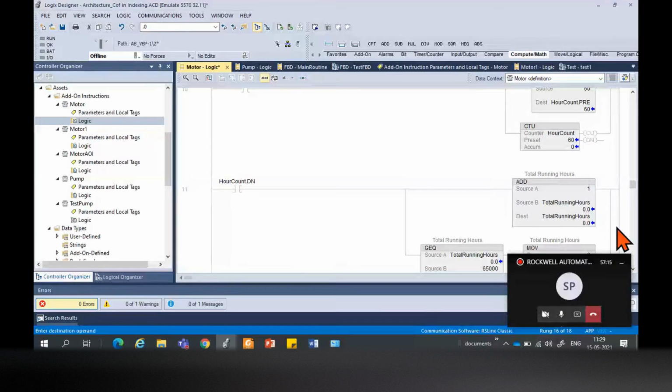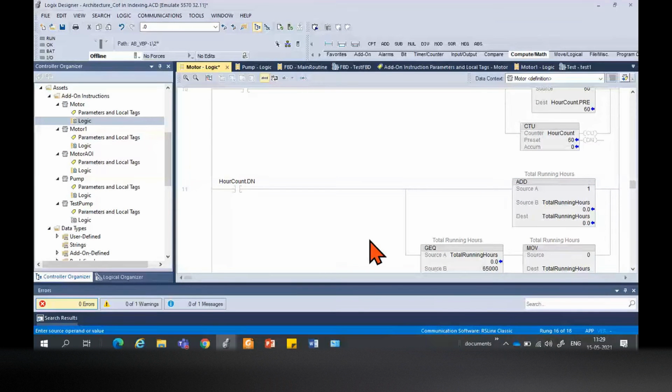Ganesh, in the motor block, suppose I want that there is a specific time, say four o'clock. If every evening at 4 o'clock I want to start the motor automatically from the block, is it possible to write an equation for that? Yes. By using the standard GSV instruction, we can start the motor every 4 o'clock or like that. Whatever time you want to set, you can set it by using SCADA or by using your logic also you can start it.